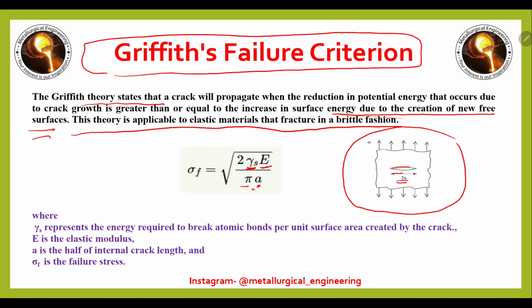If in a numerical problem a surface crack length A is given, you have to use that A directly. But if the internal crack length is given, then you have to use half of the internal crack length here. You can remember this.